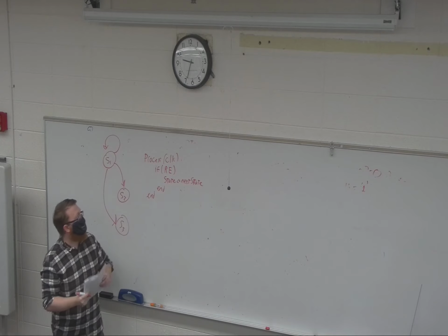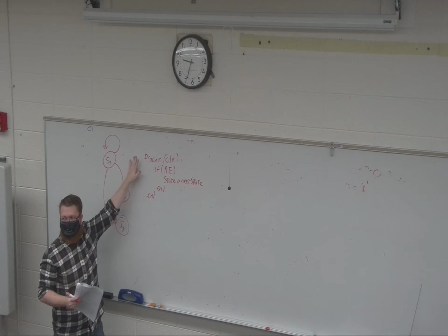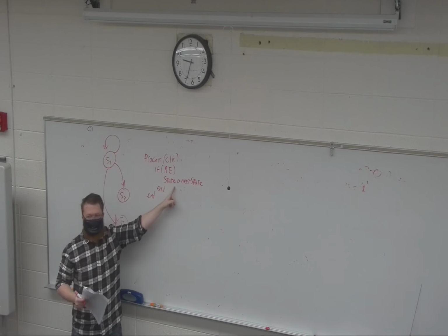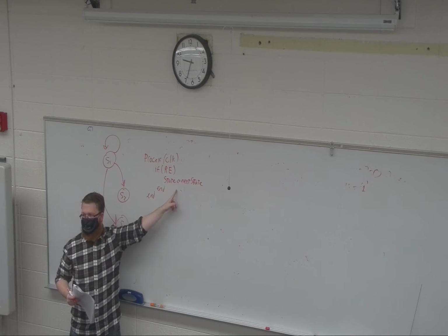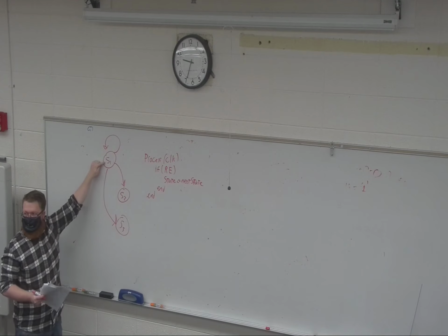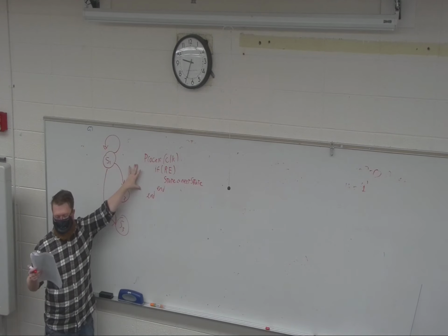And I'm going to point out the shorthanding. Normally I'd write end if and end process, but I always shorthand that just while I'm writing on the board. So all this is doing is every clock, the state is taking the next state, right? But the next state might be the same state, right? So that guy is always just kind of ticking away, doing what it needs to do.